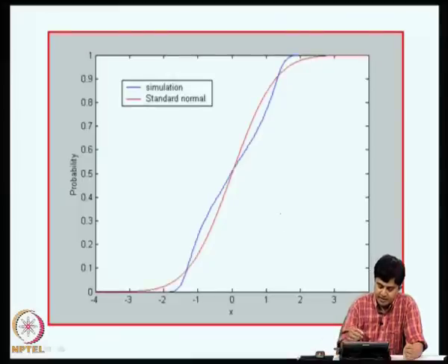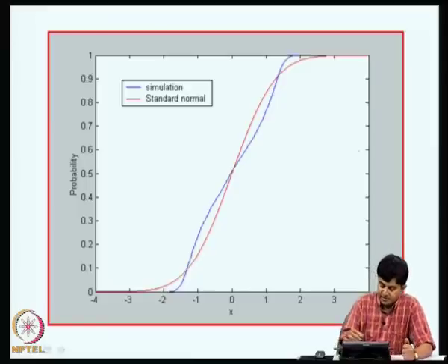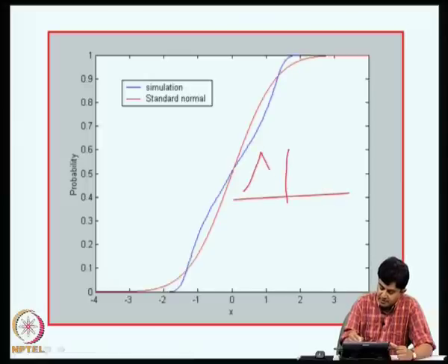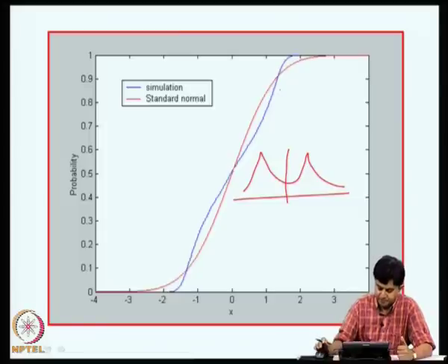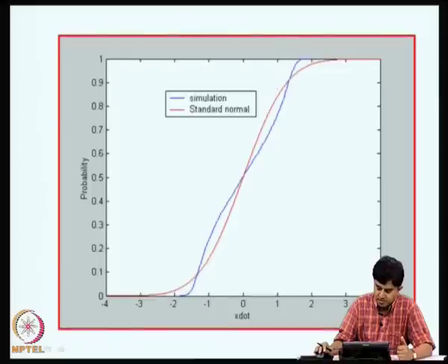You can see here that when we compare the probability distribution function of the displacement in steady state with the standard normal variable, there is significant departure. In fact, if we plot the probability density function, it will be bimodal and it will appear like this, and in the probability distribution function it will appear as this kind of wavy blue line that we are seeing here. This was on displacement, this is on velocity, and the same features are observed here also.